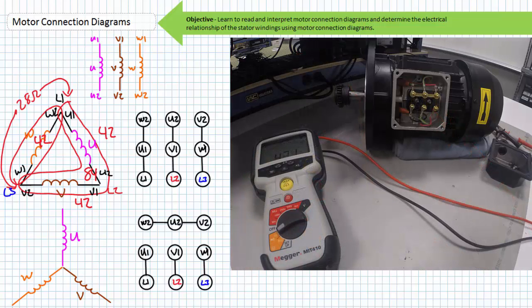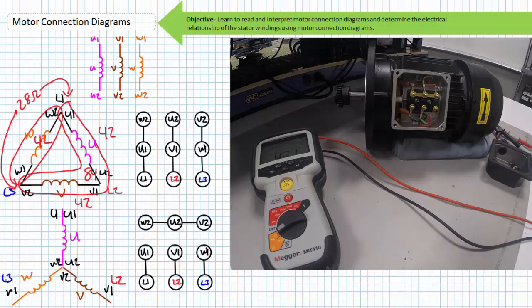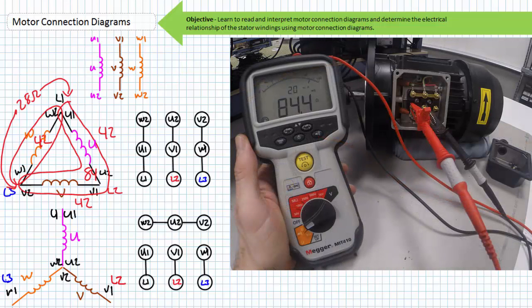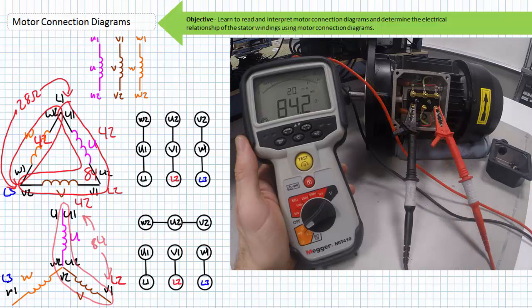Using the cheat sheet, we can now remove the jumpers and reinstall them as recommended to produce a Y configuration. Using the angularly offset terminals, 2 jumpers connect the 3 terminals U2, V2, and W2, forming the central junction of the Y. Terminals U1, V1, and W1 would be used for connection to the 3-phase AC source, where phase sequence determines direction of rotation. Note that an ohm meter used to check resistance from either corner of the Y sees around 84 ohms, which is a series combination of any 2 windings.